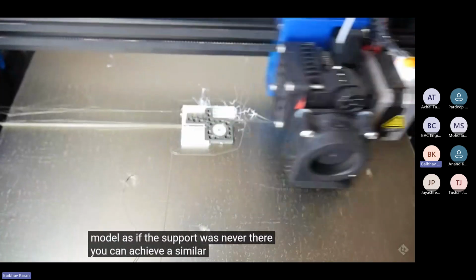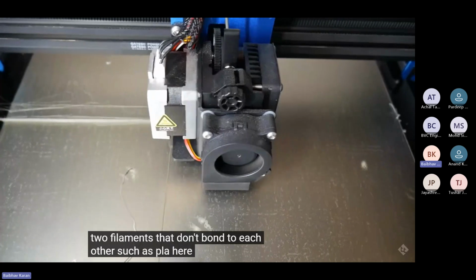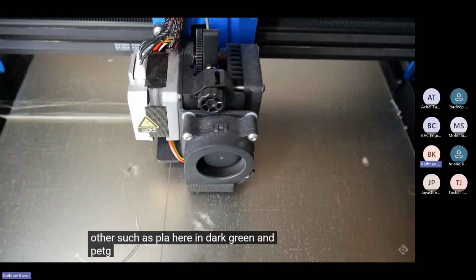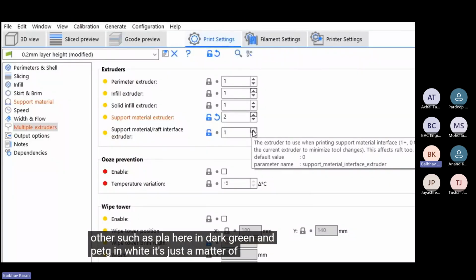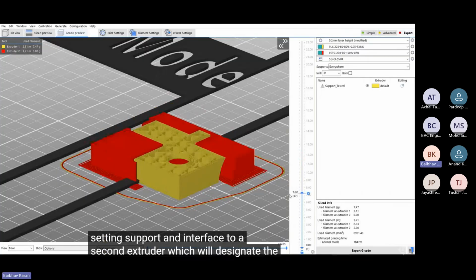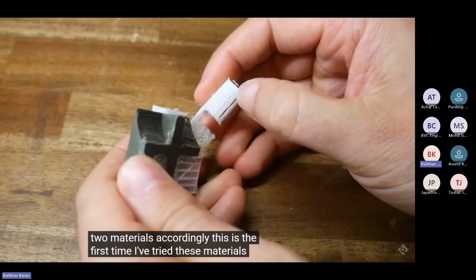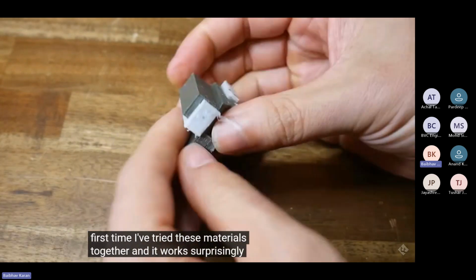You can achieve a similar effect with two filaments that don't bond to each other, such as PLA here in dark green and PETG in white. It's just a matter of setting support and interface to a second extruder, which will designate the two materials accordingly. This is the first time I've tried these materials together and it works surprisingly well.